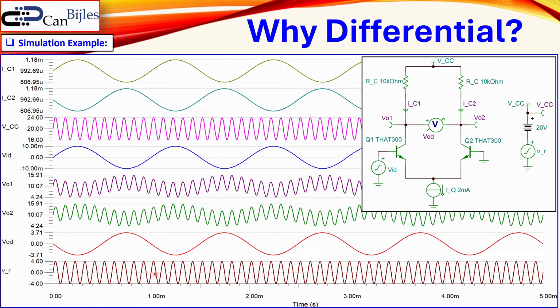And it has a very high frequency compared to the input signal, in this case the VID. So we will have here a summation of the DC quantity, 20 volts, plus this 4 volts peak for our sine wave with specific frequency. So that will be exactly put in here. So what happens now? Let's go in detail. This is now the differential mode input signal, which is our blue signal, which is 10 millivolts peak.